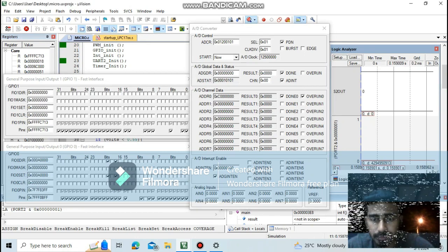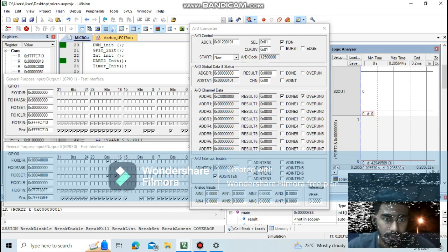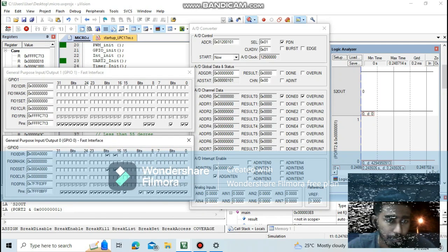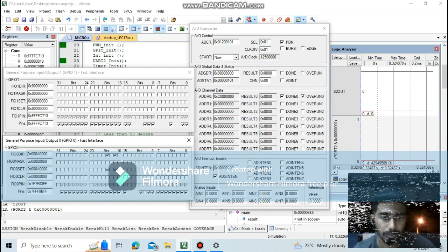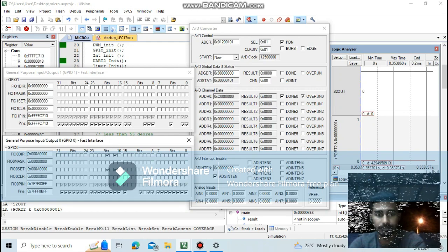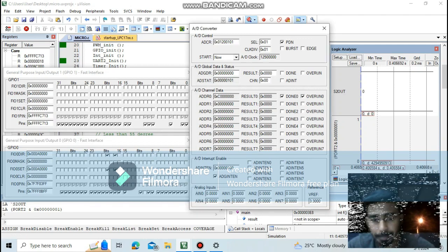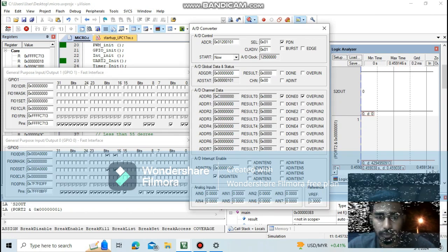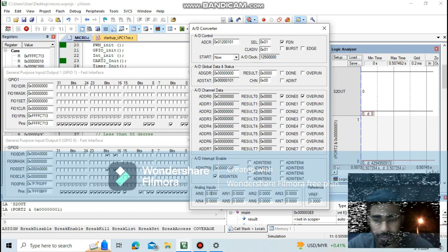Okay, here is a push button, and this is a push button for start and stop reset. And here is our heater controller, and there is a stop button in our pin 0, and here is the temperature setting for the voltage on the analog input. So now we're going to set below 55 degrees, so I set it to 5.